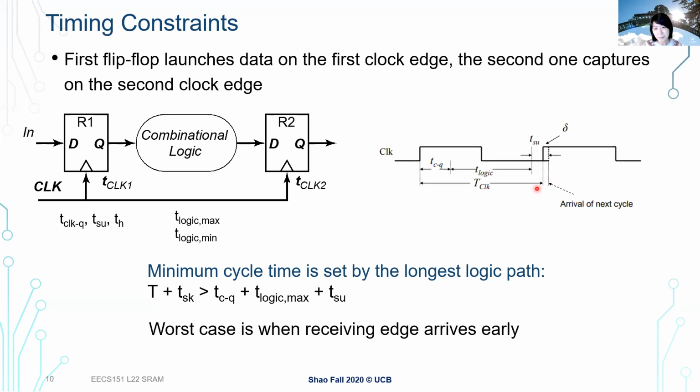So if we think about the timing analysis, we could still have our clock, but now when we think about the entire delay, we basically only need to make sure that my skew here, in this case, where my second clock is later, so we have a positive skew, needs to be greater than the clock to Q delay, the logic propagation, and also the setup. So that's something we need to consider: where the skew is, whether it's helping us or hurting us.